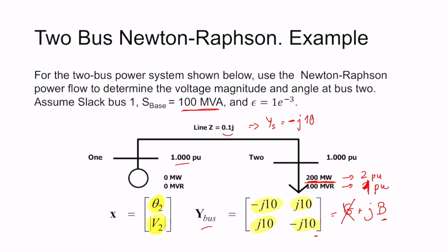So probably the first guess that I can give is 1. For the voltage phase angle, theta 1 is 0, so delta 2 could be close to 0. It's not 0, it should be something different from 0 to have some power transfer, but it is potentially close to 0. So I can start with 0.